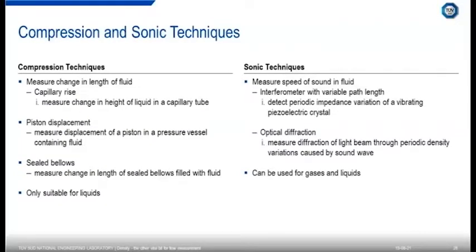And I'll just briefly mention the other two techniques I had on the introductory slide, which are compression techniques and sonic techniques. Again, a number of variants of compression techniques. We can measure the change in length of a fluid. That could be done using capillary rise, i.e. the change in height of a liquid in a capillary tube as you change temperature or pressure.